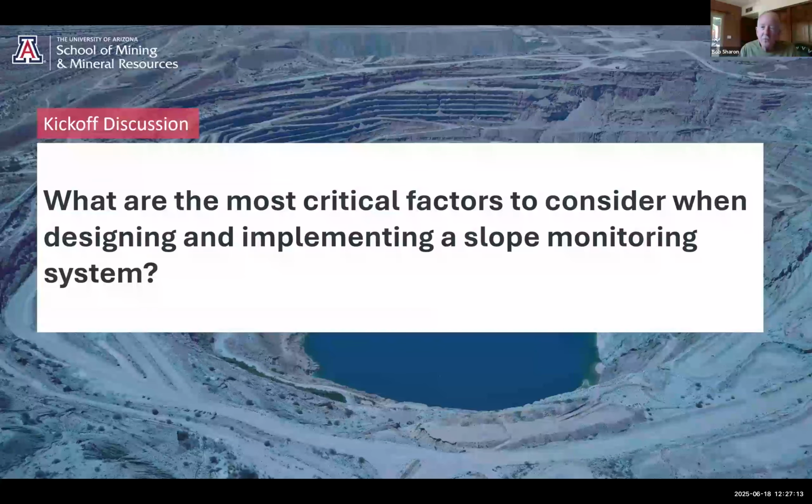So one of the things that I ask them is, okay, you've got all this wonderful radar data. The graphics look wonderful. You can see the patterns in color. That's all great, but it's still line of sight. So when I ask them, what's the total movement? They can't tell me. They have prisms out there, but they're not utilizing total vector or component vector data. Not a hard thing to do as long as your monitoring systems are functional. But they're afraid of the error that they get. And I said, don't be afraid of it. If you've got it, try to figure out why you have it.